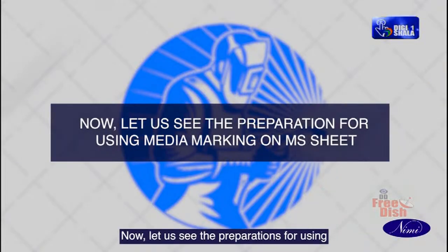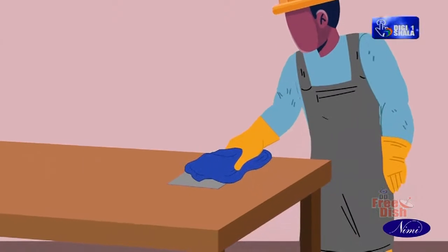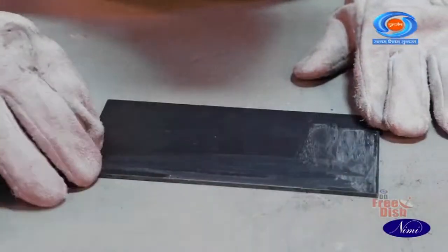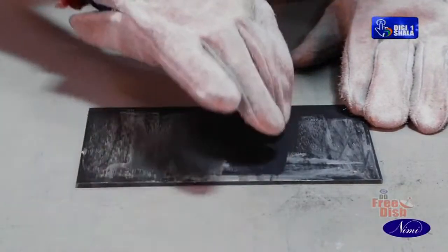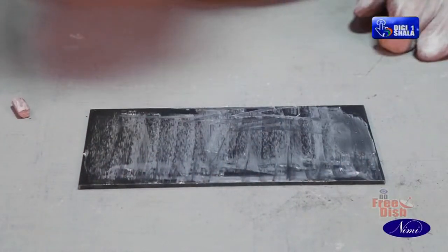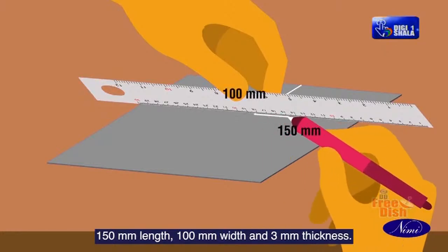Now let us see the preparations for using marking media on MS sheet. Take a 3 mm thick MS sheet for this job work. Clean the sheet with wire wool and remove the dirt and dust on the sheet. Mark the cutting edge of the job as per size 150 mm length, 100 mm width and 3 mm thickness.